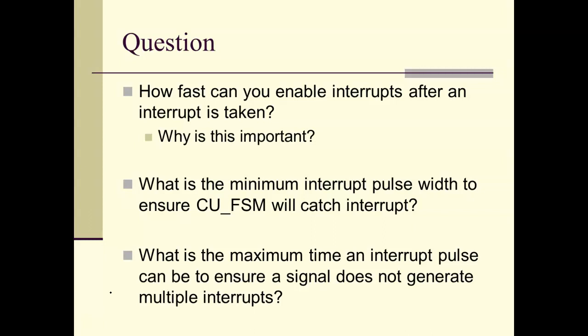Other thing here is I want to know officially the minimum time required for that interrupt pulse, such that the state machine catches it. But I also want to keep it short enough that there's no possibility whatsoever that I could ever have that interrupt still there by the time I'm done processing my interrupt service routine.